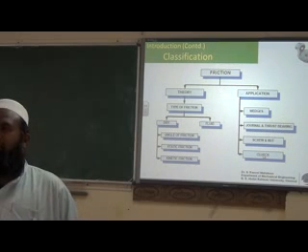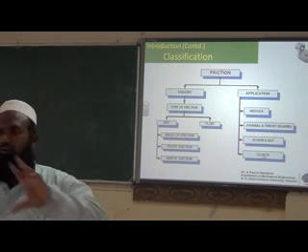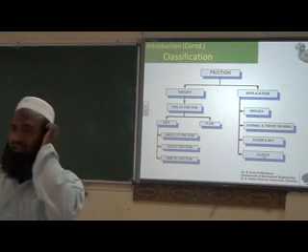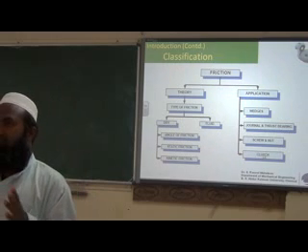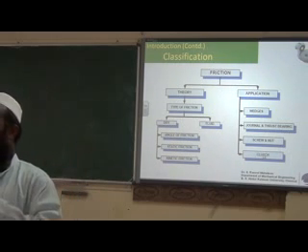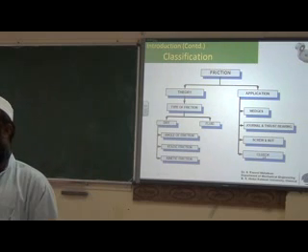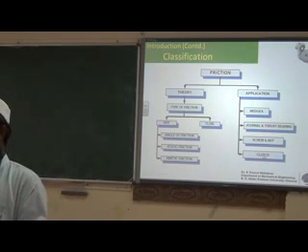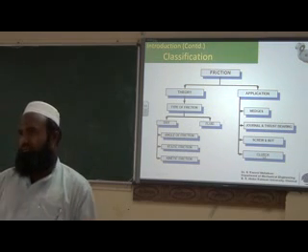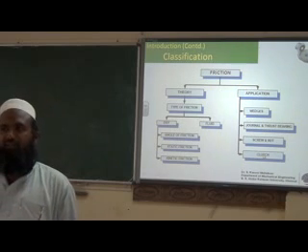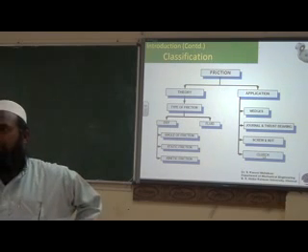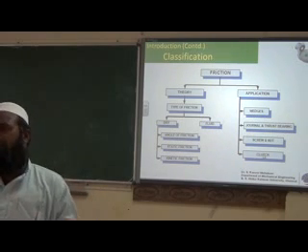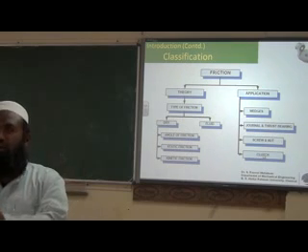Actually, if you want to stop the vehicle, you have to connect a rotating member with a stationary member. Both have two bodies. Okay. In a brake, we have a rotating body and a stationary body. If you apply the brake, the rotating body is connected with the stationary body, so it will also come to rest, like the stationary body. Whereas in a clutch, both are rotating bodies. One rotating body is connected to another rotating body.